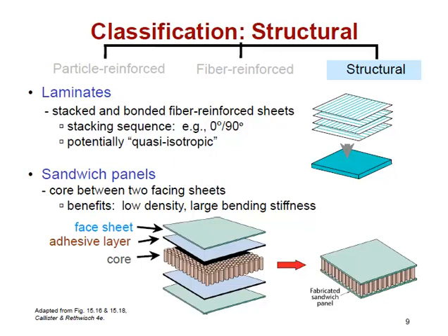they're not very thick. Sandwich panels are far more complicated, and in this case we have what could be just monolithic materials, a face sheet, it could be a continuous piece of plastic, a thin layer of metal, and then we'll have an extruded or possibly additive manufactured core, usually in a honeycomb or other kind of hollow, lightweight structure. And then they're adhered together with structural adhesive. This is so that the load can transfer very uniformly. And all of these pieces are very, very thin.